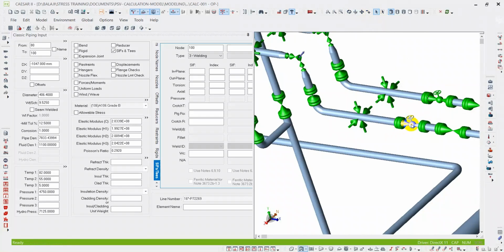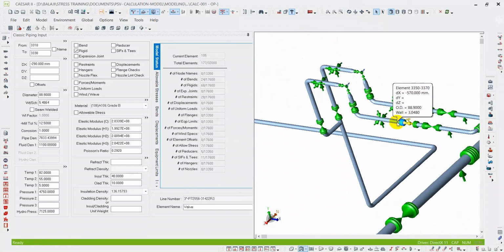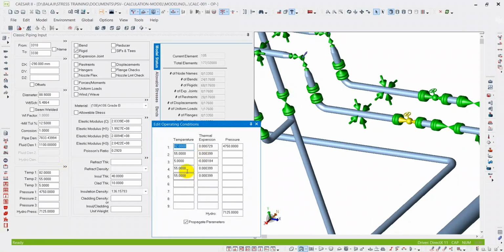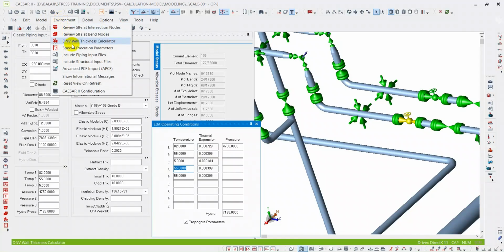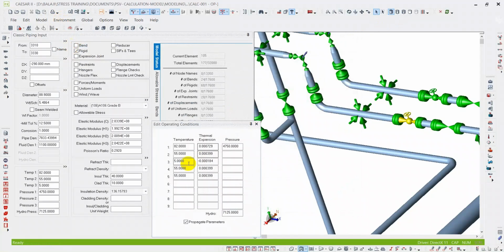So that means you select this one, because from this onwards only, if you close this one, there will not be any fluid. So from this point, you select this one, temperature, double click this double arrow, and from here onwards, there will not be any fluid. So that means you have to consider the ambient temperature. What will be your ambient temperature that you have to consider from your design basis? So already we have defined ambient temperature as 21 degree.